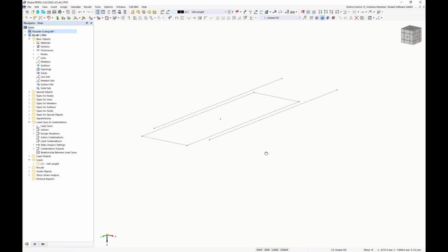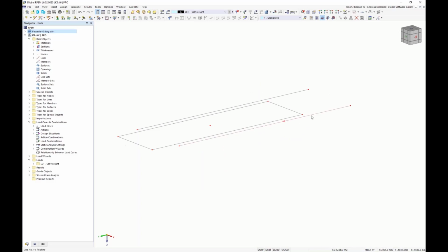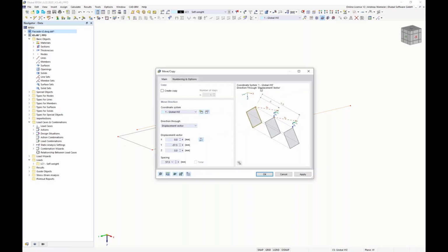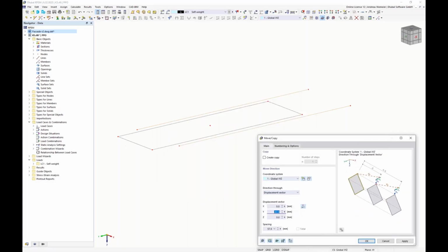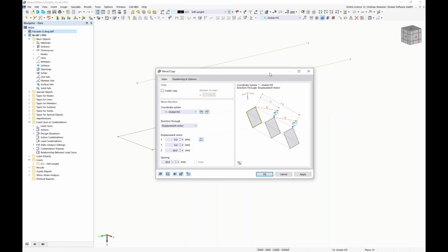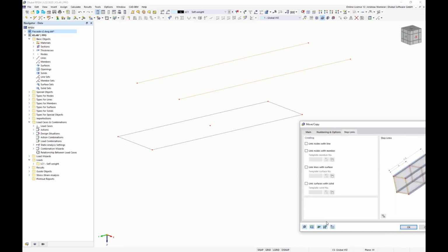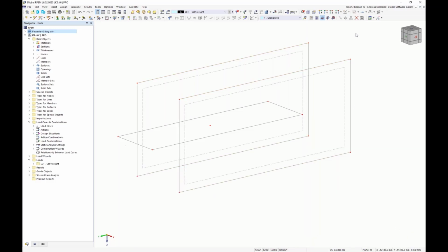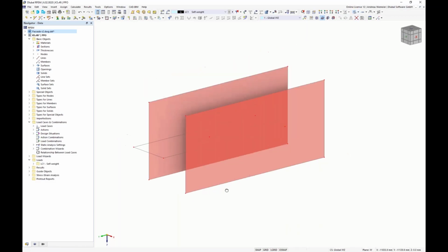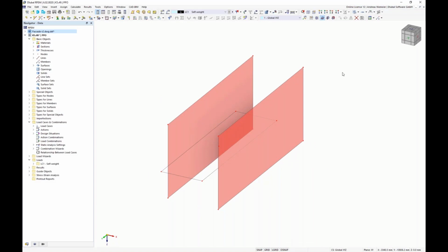Now let's create the first metal surfaces. Therefore, I select both lines and move them a little bit upward at first, here with minus 50 millimeters. And now we draw, moving it down with a copy with 100 millimeters, a new surface by defining the vector, and here by using step links, by saying please create a surface in between, and if I confirm it, I get my surfaces from these elements.